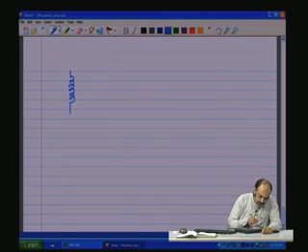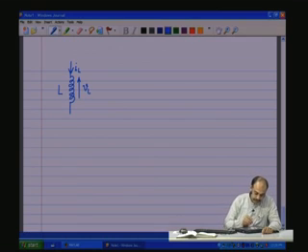we have the inductor L, there is a state variable which is the current flowing through L, and there is the voltage across L, VL. Now, the dynamic equation for this is L dIL/dt equal to the voltage across L, which is VL.